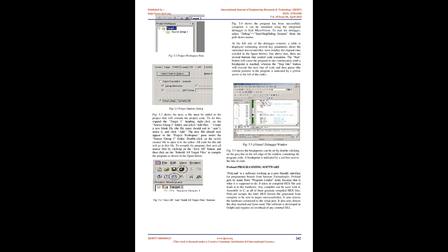Create source files to add to the project. Select Project, Targets, Groups, and Files. Add files, select Source Group 1, and add the source files to the project. Select Project, Options and set the tool options. Note that when the target device is selected from the device database, all special options are set automatically. Default memory model settings are optimal for most applications.